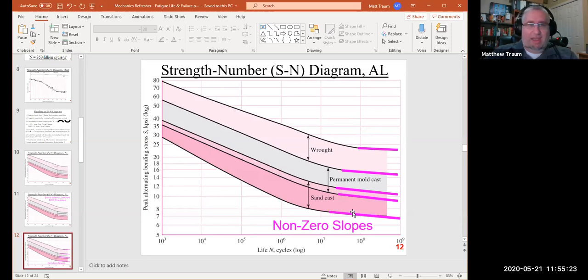And remember, in the aircraft industry, especially in the days before composites, everybody wanted high strength and light weight. So a lot of aircraft components are made out of aluminum, the MD-80 is made out of aluminum. Hence you get those failures that were so prevalent about 20 years ago in the aerospace industry, because they made their parts out of aluminum, and poof, they crossed one of these curves because those parts were left in service for way, way too long.